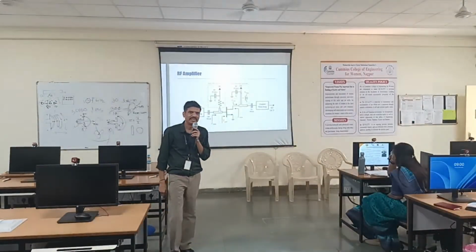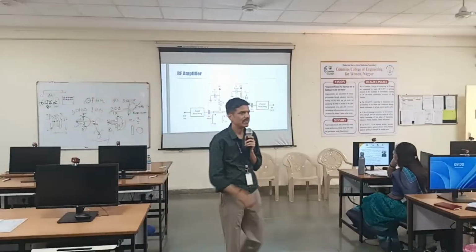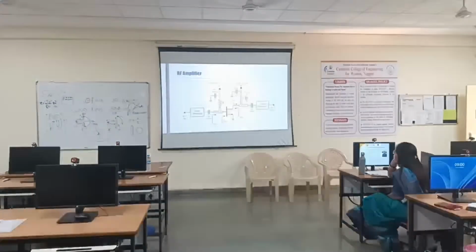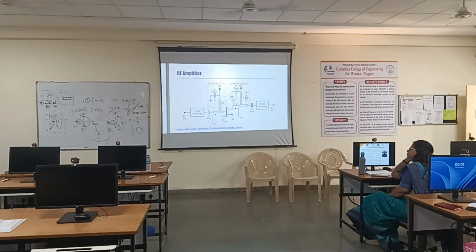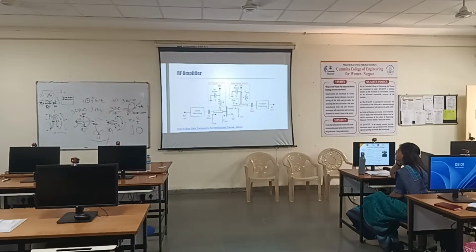This is the actual PA schematic you can see. We have a transistor in between. We place one set of transmission lines here and one set of transmission lines here, right? And this is just for the DC bias purpose. We have an RF bypass capacitor, we have a resistor in between. Typically we put this resistor in RF PAs. We can use an inductor or a lambda by 4 section transmission line here. What is the need of this? No, this we don't use for impedance matching. This lambda by 4 line has its own importance. Lambda by 4 line transfers the impedance.